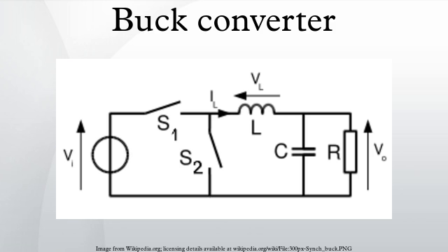A converter expected to have a low switching frequency does not require switches with low gate transition losses. A converter operating at a high duty cycle requires a low side switch with low conduction losses.